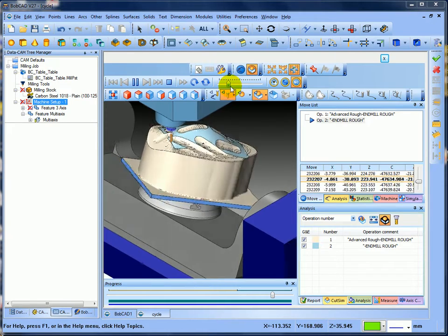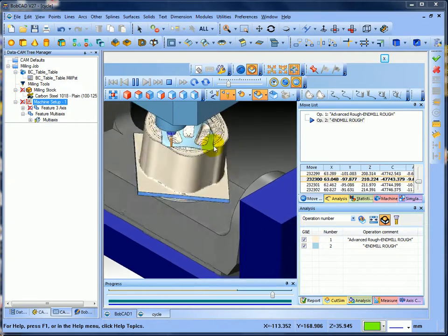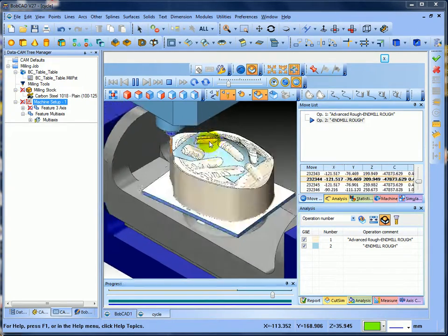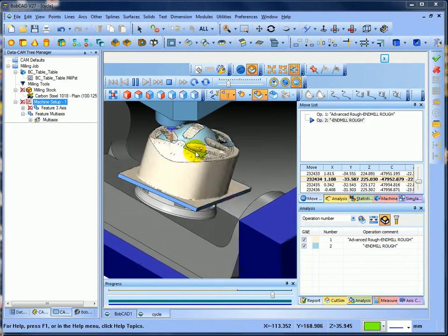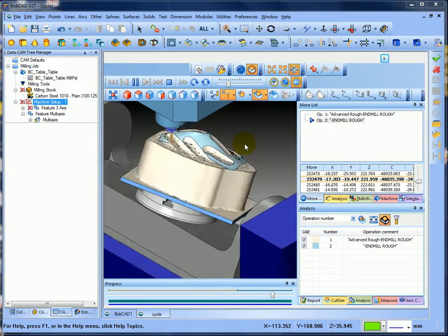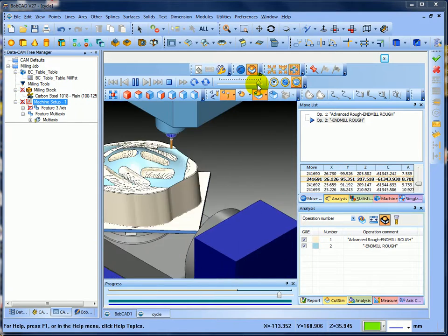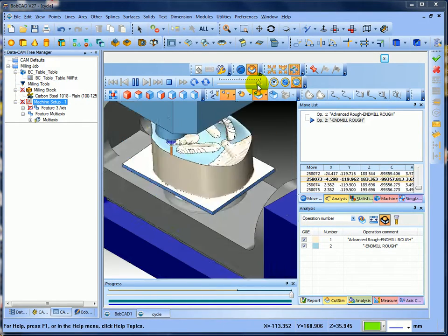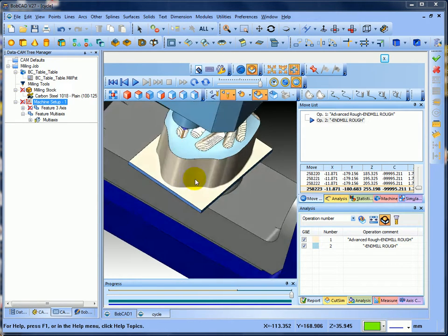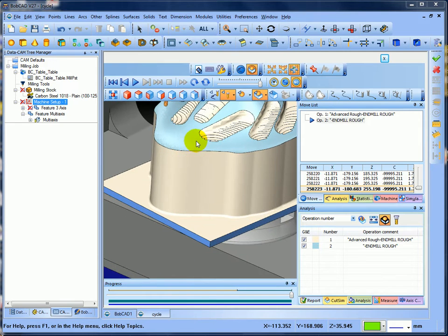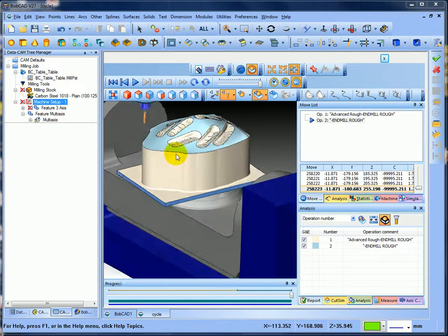So you can see it machining just that surface without falling down anywhere, doing the 5-axis simultaneous. Let's move it a little bit further forward. And you can see I've machined up this area just using 5-axis, using a multi-axis, using it on a trunnion fixture.